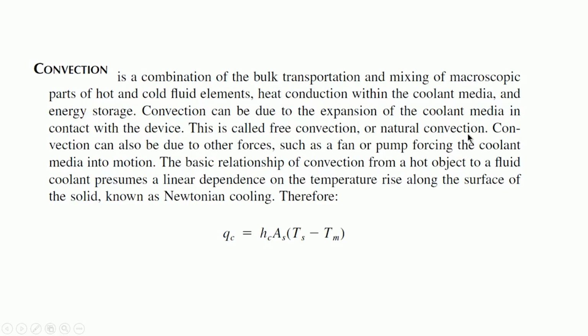So, we have this issue of two things called natural convection and forced convection. In the case of natural convection, the expansion is the one that aids it. But then, the reality of natural convection is that the orientation of the fins is critical. It should be in the same direction in which the fluid is flowing. Maybe in the next picture, I will show you a picture of a printing head which moves in a printer.